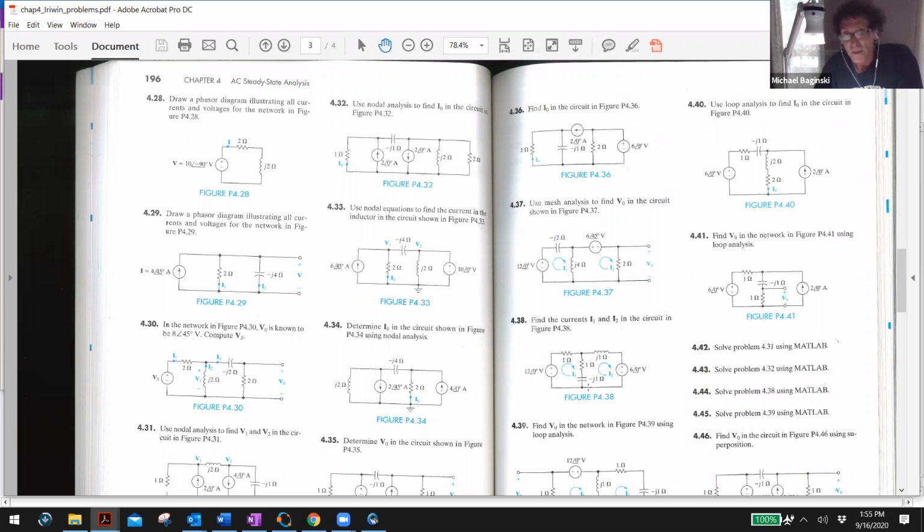Just think of that as an impedance Z. So it's going to be minus that impedance, minus Z times the net current flowing up, which would be I2 minus I1. Agree? Okay. So it's minus Z, which happens to be 1 minus j1, times the quantity I2 minus I1. Then it's minus j1 times I2, and then minus 6 equals 0.